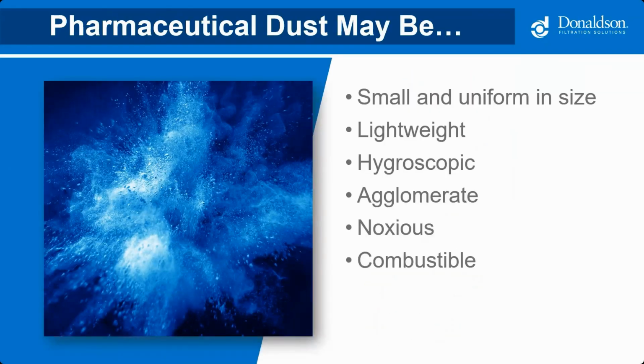So let's talk about common properties of pharmaceutical dust. It's typically small and uniform in size. It's lightweight, hygroscopic, meaning it attracts moisture. So any wet applications or any introduction of moisture to a process can cause that particulate to become extremely sticky, and then it has a tendency to dry and become a hard crust and blind off filtration. So that can be a challenge.